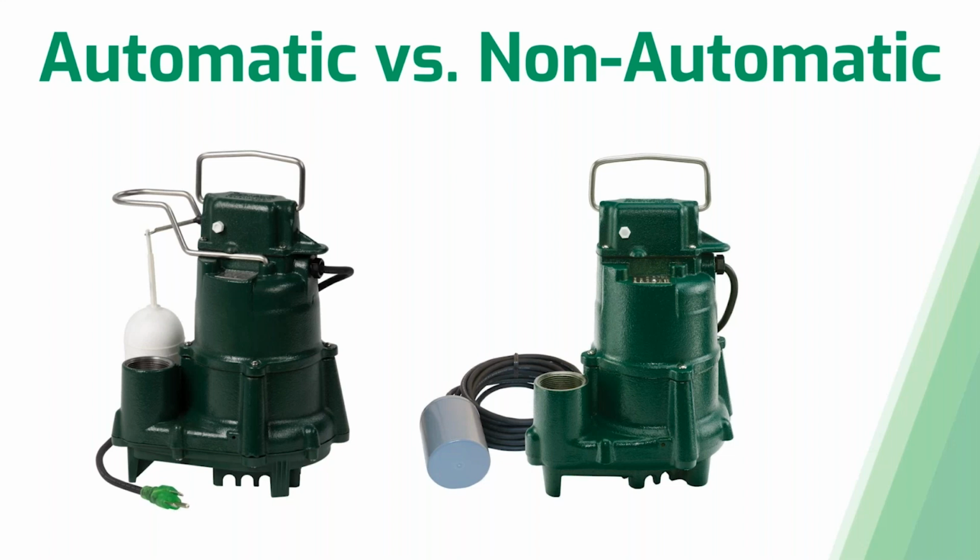So you'll see them in residential and light commercial and even more commercial facilities that need a lot more flow capability. With non-automatic pumps, you typically have much more control over when that pump turns on and off, so you can set your float switches in any configuration that you want in order to ensure that you're pumping the right amount of water out of your system to fit whatever the incoming flows are.